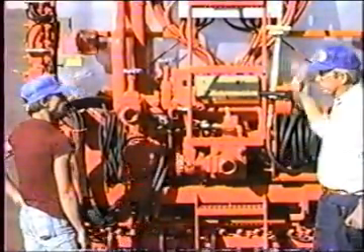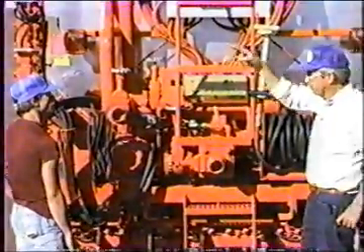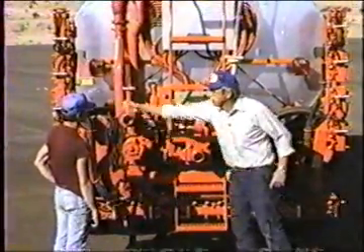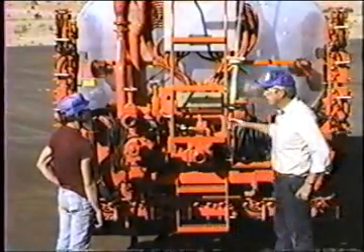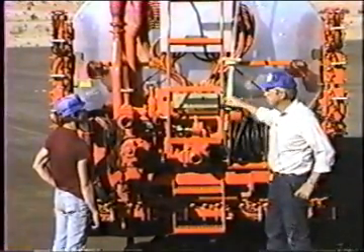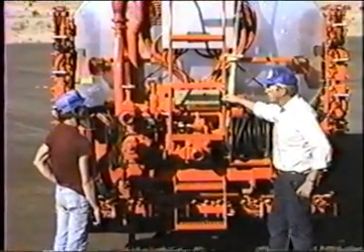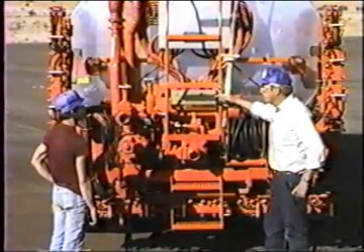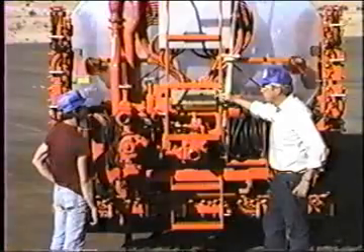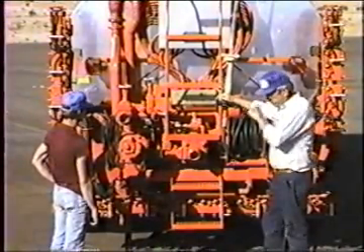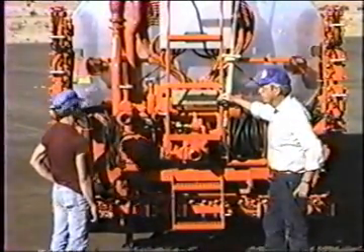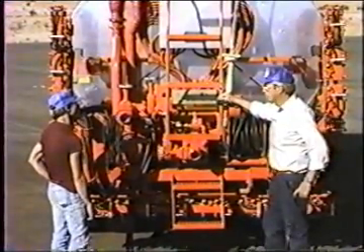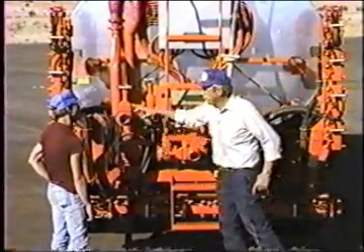Another situation, this tank over here to that tank over there. We could pull in the bottom here, in the bottom, out the top here. We can go either direction through the pump. We can do it in any combination. That's what happens to be the easiest. One thing to keep in mind, this pump has a relief valve. But the only direction the relief valve works in the pump is in the forward direction, that is in the bottom and out the top.